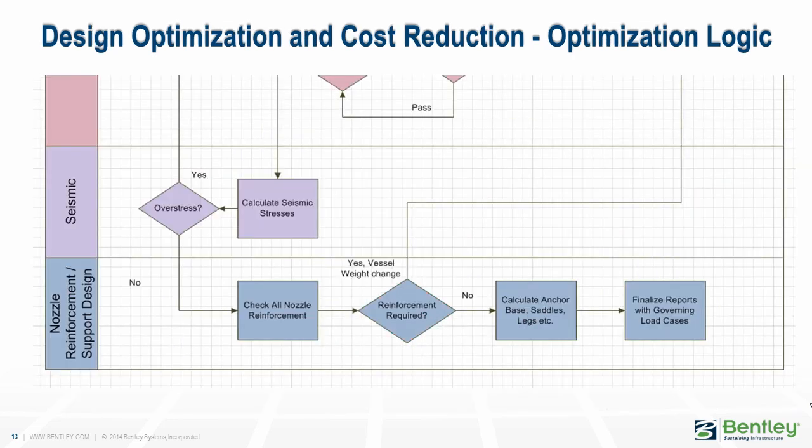If the seismic calculation fails, the thicknesses are revised, else it proceeds towards nozzle reinforcement check and performs necessary optimization action for nozzle design. Finally, the calculations for base, anchor, saddle, etc. are performed and the report generated with the load case calculations.